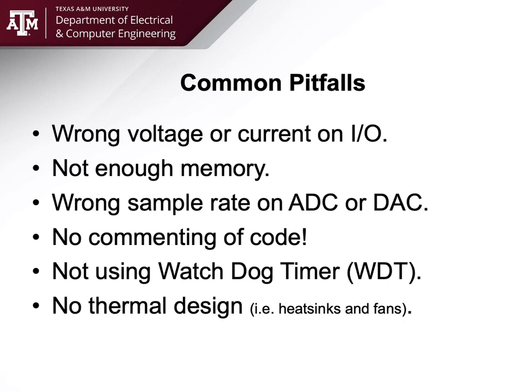Not using a watchdog timer, we kind of bang that one pretty good. And again, this one highlights back to what I mentioned earlier: no thermal design. In the end, microprocessors and microcontrollers generate heat. It might be a small amount of heat, it might be a watt or two or half a watt, depending on what's going on, but there is heat being generated. If you put that in an enclosed space with no fan circulation or no air venting of any kind, eventually that heat builds up and will destroy the chip. So make sure there is some sort of ventilation or some way to reject the heat.